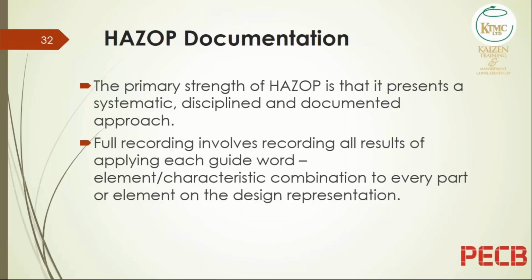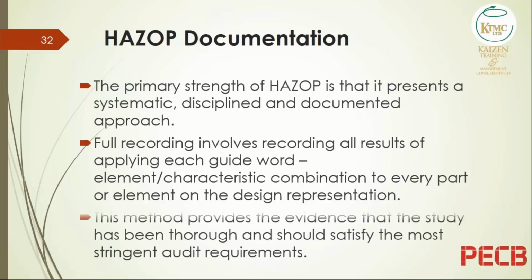Full recording involves recording all results of applying each guide word. So as you look at flow, no flow, high pressure, low pressure, everything is recorded, all possible deviations. This method provides evidence, so the documentation provides evidence that the study has been thorough and should satisfy the most stringent of audits.